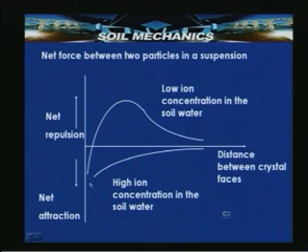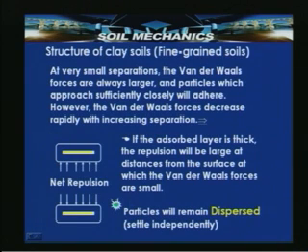So, particles very close together have a strong attraction, because of the van der Waals forces. That is what has been told here. At very small separations, the van der Waals forces are always larger, and particles which approach sufficiently closely will adhere. However, the van der Waals forces decrease rapidly with increasing separation. Here a clay particle with an adsorbed layer is shown, and they are subjected to repulsion. If the adsorbed layer is thick, the repulsion will be large at distances from the surface at which the van der Waals forces are small.